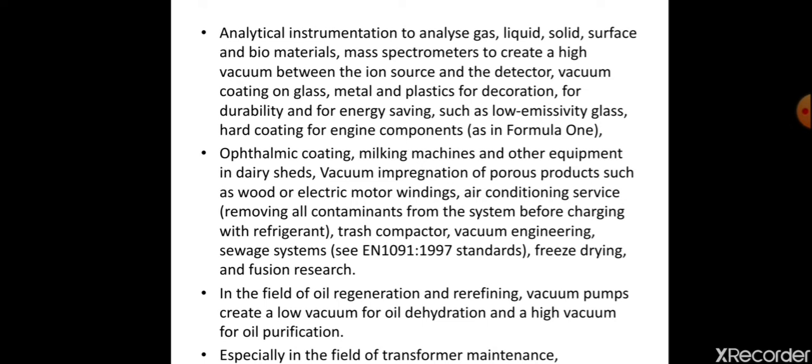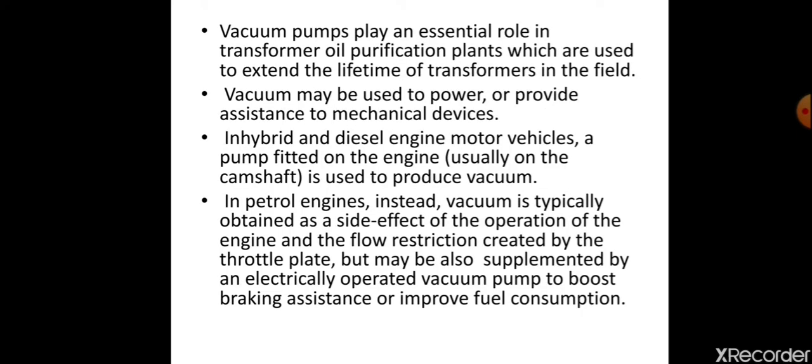and fusion research, in the field of oil regeneration and re-refining. Vacuum pumps create low vacuum for oil dehydration and high vacuum for oil purification, especially in the field of transformer maintenance. Vacuum pumps play an essential role in transformer oil purification plants, which are used to extend the lifetime of transformers in the field. Vacuum may be used to power or provide assistance to mechanical devices.